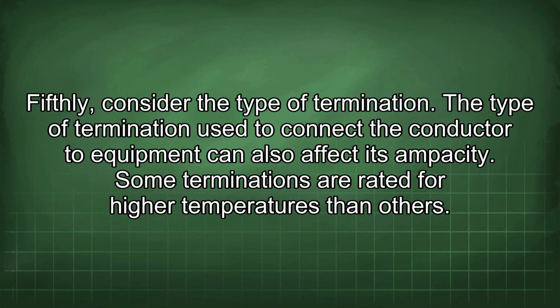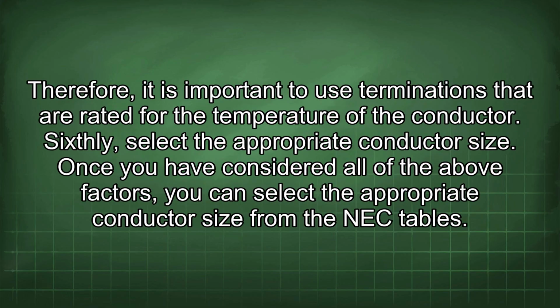Fifthly, consider the type of termination. The type of termination used to connect the conductor to equipment can also affect its ampacity. Some terminations are rated for higher temperatures than others. Therefore, it is important to use terminations that are rated for the temperature of the conductor.